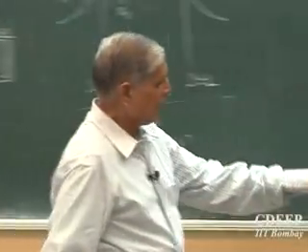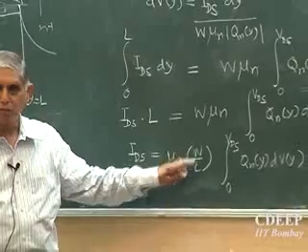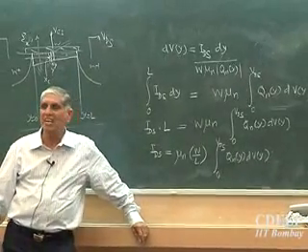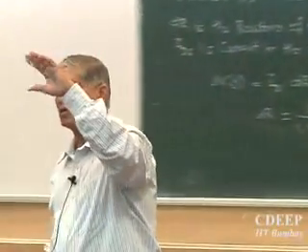Is that point clear? Another issue before we actually solve this is W by L. What does that mean? The word I just said a few minutes ago was scaling. What does scaling mean? The dimensions are scaled by some number. Let's say I have 1 micron technology, I say okay, I want half a micron, so put everything down by 50%. Channel length will reduce, channel width will also reduce. So W by L doesn't change. If I scale, W by L doesn't change. Individually length may change, width may change, but the ratio does not change. Current is therefore not proportional to the technology directly, but it is proportional to the ratio W by L. This is most important in design, that it's the ratio which is giving me current and not the values of the individuals.